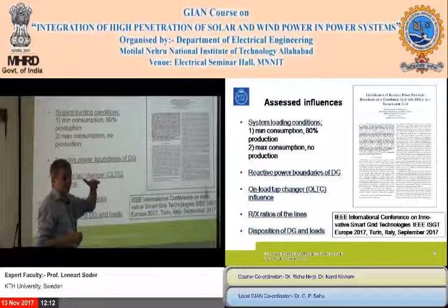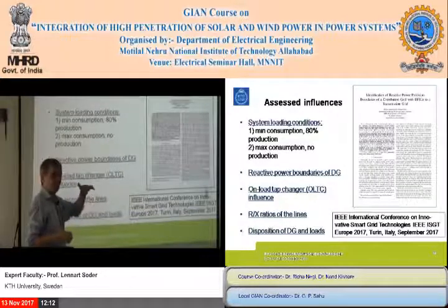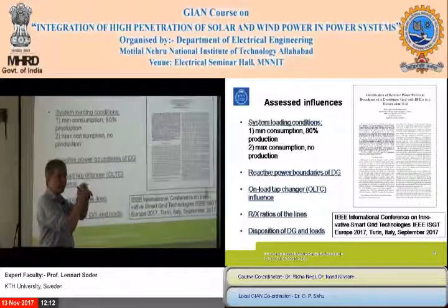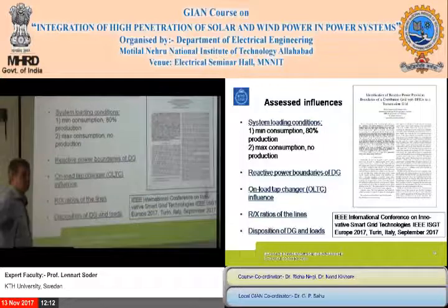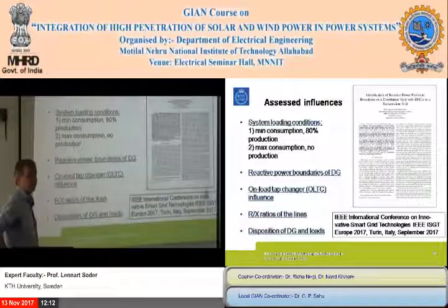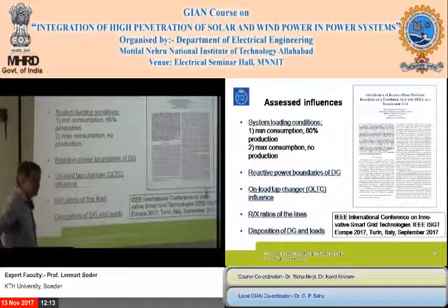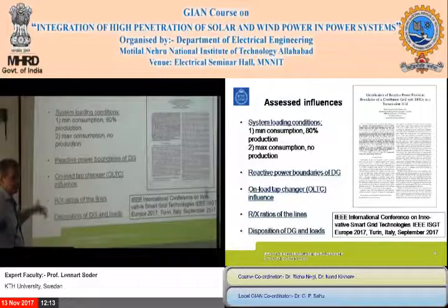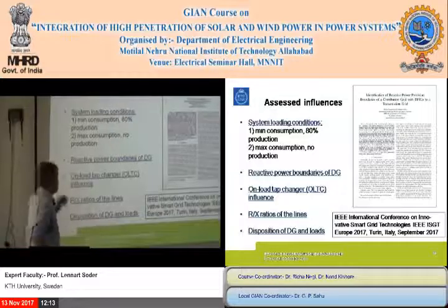If you dimension it so that it is only enough for the active power, then of course you cannot supply any reactive power. But normally, what I understand is that you normally over-dimension the converter a little. The question is how much, because that has an impact on the possible reactive support in maximum production. So you have to think about this when you are dimensioning your wind power plants, if it costs something extra to get an over-dimensioned converter, for example. So that is, of course, important.